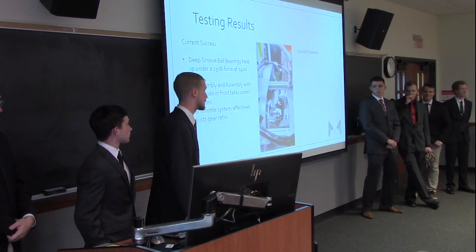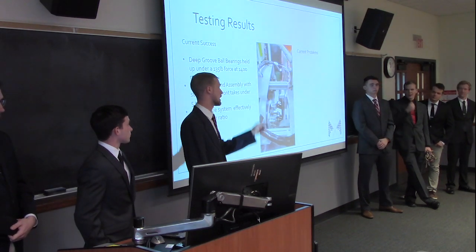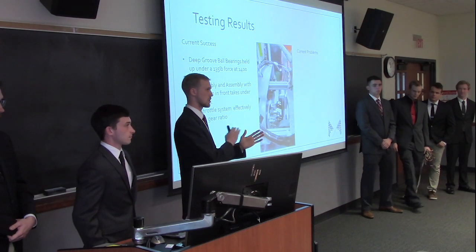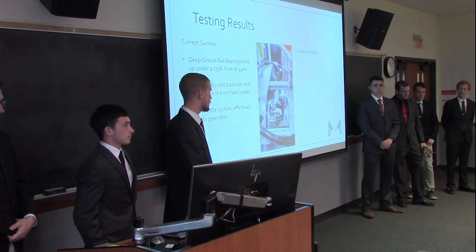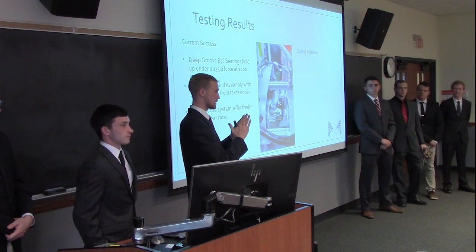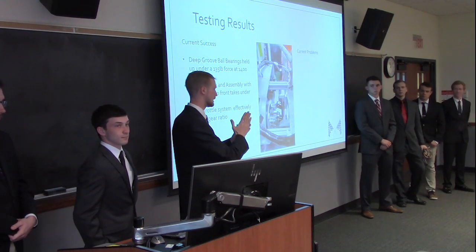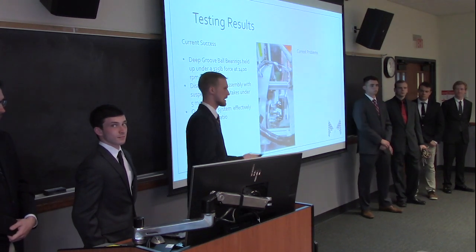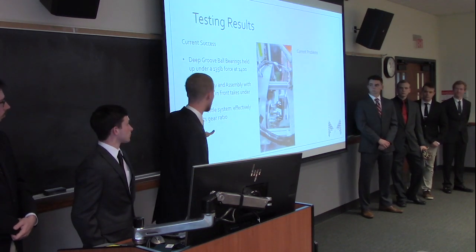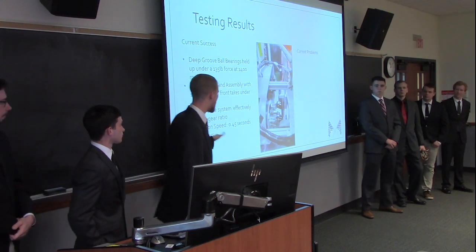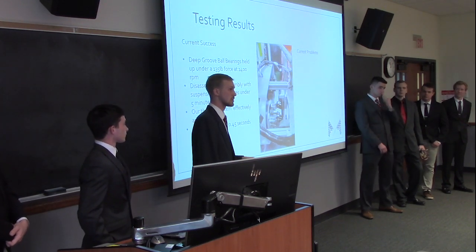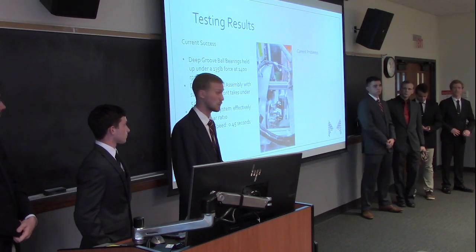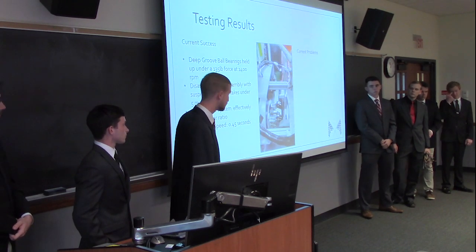Our throttle system effectively does adjust the gear ratio, the throttle system that Dane was talking about. We were able to push the pedal a little bit back and forth, and we could see that the pulleys stayed a certain distance up until we hit the spring, and then as we pressed on the spring, the pulleys started to close together, which was that eco sport mode. So it worked just as we thought it would. The actuation speed is 0.45 seconds, which is a lot faster than the 0.7 seconds and the 3.8 seconds that we talked about before. So this thing operates a lot quicker.